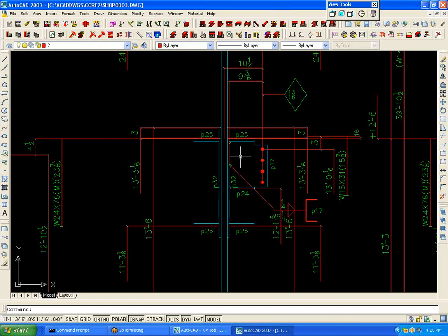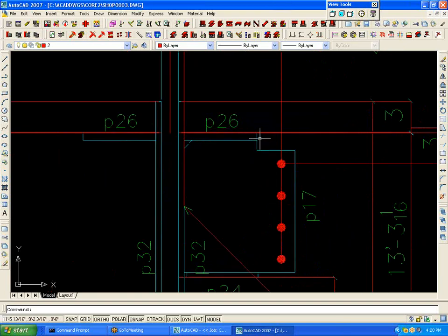Our system is a detailing system. It's not interested in showing you clashes on the screen. It's interested in fixing the situation and producing the shop drawing and calling it a day. So what the system did in this particular situation is it got rid of the half-inch stabilizer plate, because the continuity plate is much more important because it transfers the moment through the moment frame.